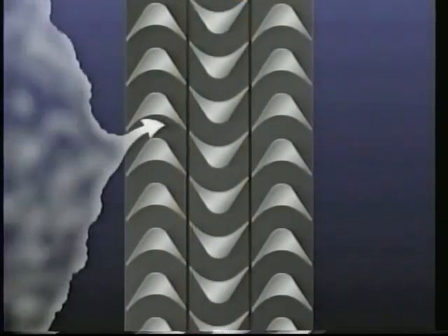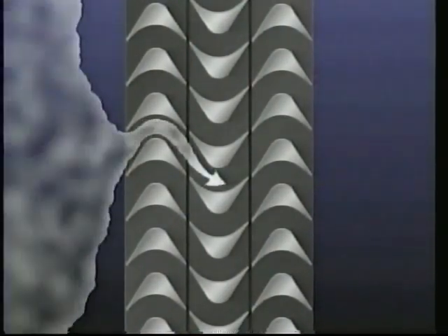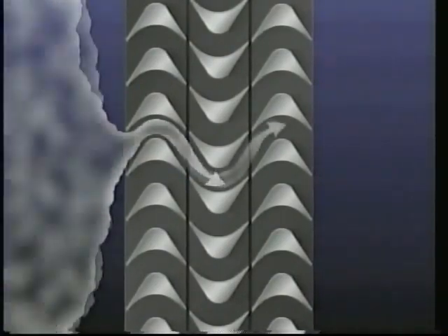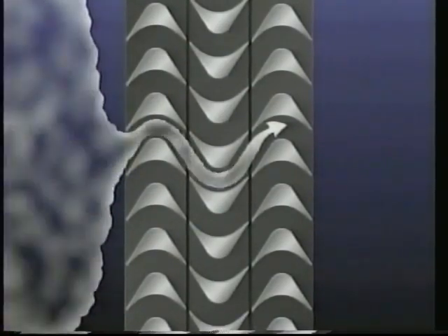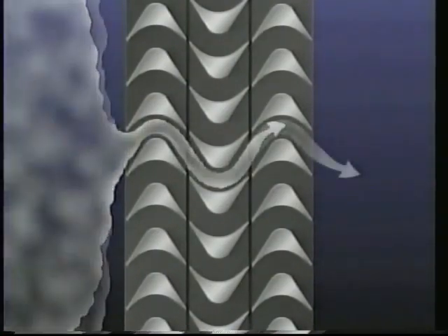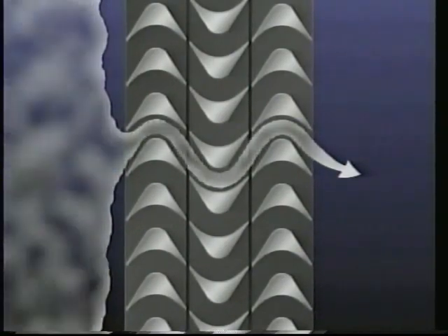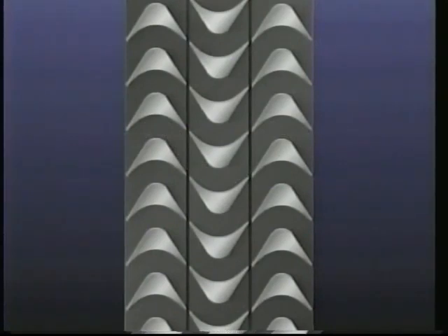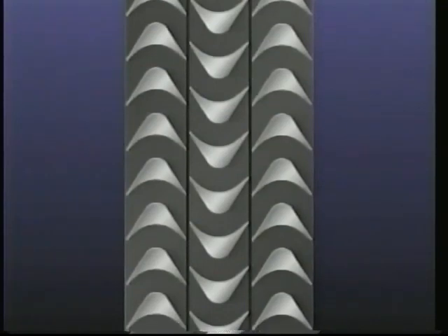The steam flows through the first set of moving blades where some energy is extracted. From here, the steam flow is routed on to the fixed blading. The fixed blading then redirects the flow of steam to the next set of moving blades so that more energy can be extracted from the steam. Once the steam has passed through the second set of moving blades, the steam is routed out of the turbine. This flow path of steam striking the moving blades causes the moving blades and the turbine shaft they're mounted on to rotate.